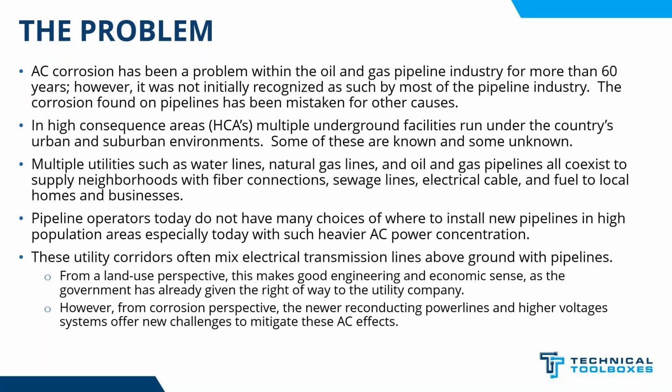this is an accident. You're not going to believe this, that our coupons that we put in there, we just happened to coat the edges of the coupons with an epoxy, a liquid epoxy. And guess where the corrosion was? It wasn't on the coupon because of the size of it. It was on the edges of the coupon where we put the epoxy. Voila, current density. And we didn't realize it. We understood the concept, but we didn't know what values at the time. But that 4-year study opened our eyes.